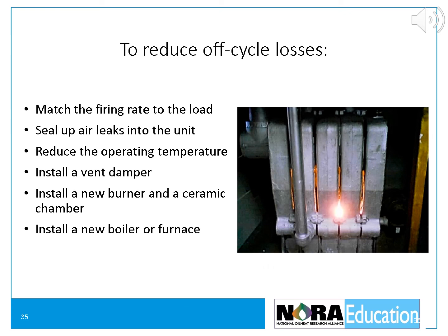The shorter the cycles, the greater the losses. Heating system sizing is an important factor that affects on-off cycling and heat loss. Oversized heating units will have longer off periods and off-cycle losses will increase. A heating unit that is closely matched in size to the building's heating requirements will provide the lowest off-cycle heat loss and highest efficiency. It might be possible to underfire an old oversized furnace or boiler to match the firing rate to the load. There are 3 times when underfiring is a bad idea.